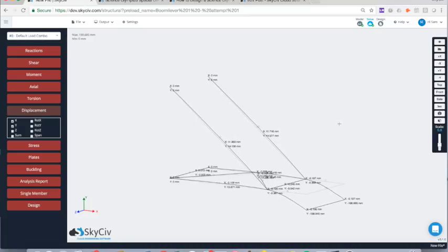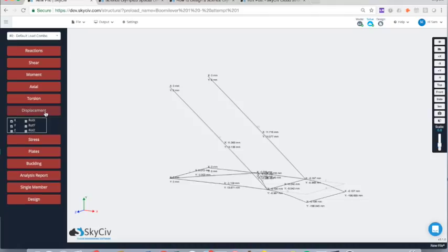So if I apply loads, I can see how it's bending there, and I can use this scale here just to animate it. But I can see the deflection is about 200 millimeters, which for a span of about 500 millimeters, that's quite a large deflection. So I can already sort of tell that this is probably not going to pass my stress test, but let's go through and check it anyway.